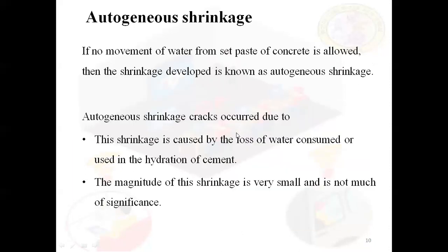Next, coming to the autogenous shrinkage. If no movement of water from the set paste of concrete is allowed, then the shrinkage developed is known as autogenous shrinkage. Generally the autogenous shrinkage occurs due to the loss of water consumed in the hydration. When there is a loss of water because of hydration or by evaporation, the autogenous shrinkage cracks will develop. The magnitude of autogenous shrinkage is small and not very important.